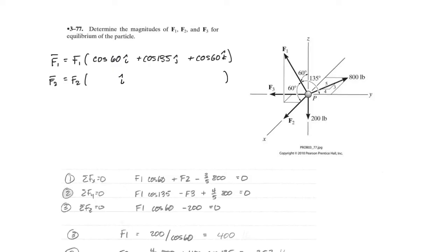And that's it. F3. Magnitude is unknown. In this case, it is only in the J direction, pointing backwards in the negative J, so I'm just going to put that as negative J. F4. All right, what does F4 look like? I guess I didn't really label it here, but I'll call this one F4. And it looks like it is negative in the K direction, fairly easy to see. So it's going to be 200 as the magnitude, which is given, but only negative in the K.